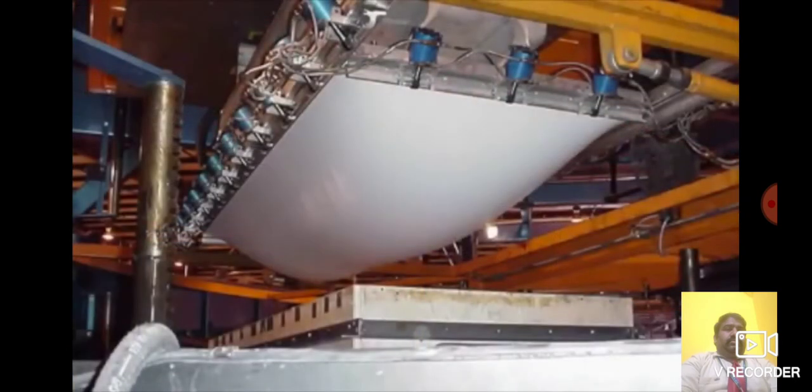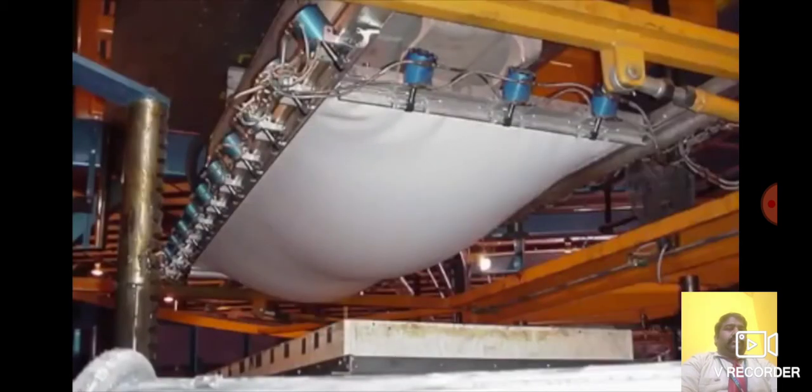As the sheet is heated, it loses strength and begins to sag. To experienced thermoforming personnel, the amount of sag and the shape of the sag is a useful indicator of how evenly the sheet has been heated and how well the plastic can be formed. For some part designs, the sheet is intentionally heated unevenly to improve the plastic distribution in the formed part.